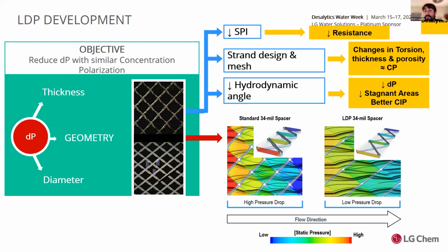Why is this? You reduce the fouling rate because you increase the cross-flow velocity. If you reduce the cross-flow velocity, then it will be easier for particles to start settling down on the feeder spacer or membrane surface. And of course, this applies not only to normal operation, but also when you are performing CIPs. So you can improve the efficiency of your CIPs.